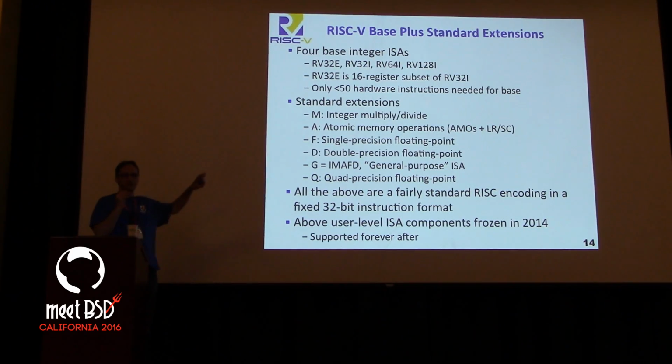For the integer base, there are fewer than 50 hardware instructions needed. And those hardware instructions give you a modern software stack. With those 50 instructions, you can build GCC, you can have dynamic linking, position-independent code, you can run an OS, everything, just with those base instructions, right? So the integer base is designed to be very, very simple. And this is a great boon for teaching. I can teach a whole class with all the tools and bring up the whole data path in one lecture, right? This is great. Then there are the standard extensions that give you other operations you'll need.